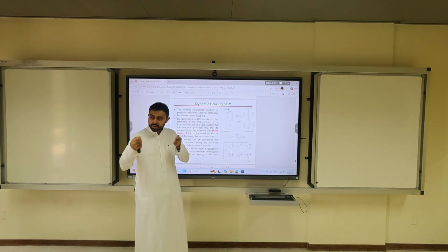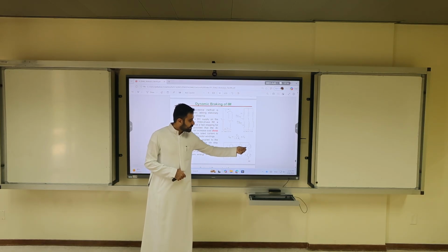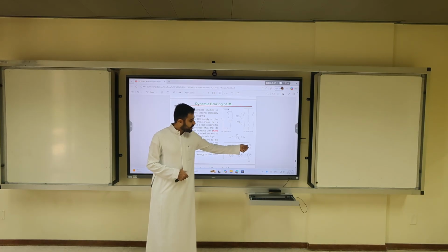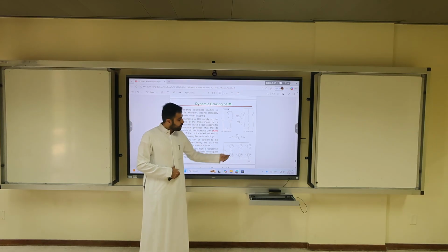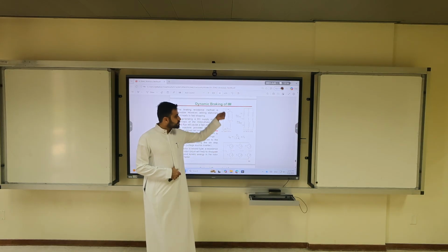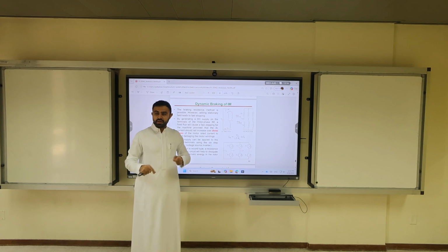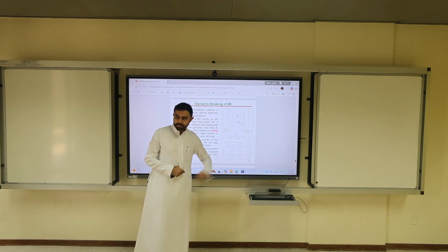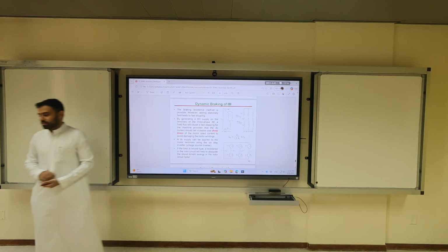So you take your DC source, you make switches S1, S6, S5. If you make S1 on, S5 on, you connect A and C to the positive. If you make S6 on, you connect B to the negative. That's why we have this connection. So you apply a DC using pulses. If you want to change, you can have another configuration. Maybe you can have 1, 3, 2, etc. But how does this work?